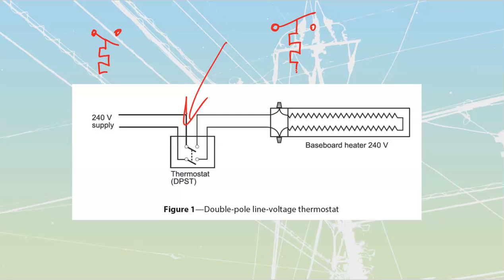That little symbol on the bottom indicates the fact that we have got temperature response for these. And what we always do is we always look at the rise in temperature, as if the temperature is rising, that it was going to go and push up on these. This one over here would make sense that we would want to go and place this thing through to a heat source, because as the temperature would be rising, eventually it would get hot enough and then it would open that circuit, shutting that heater off.